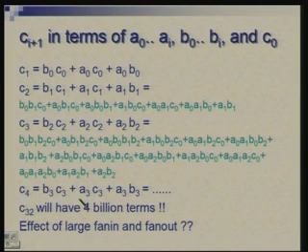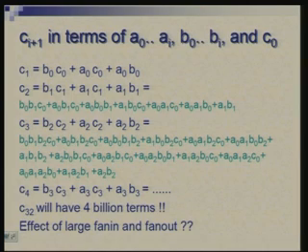The assumption we made initially, that the delay of each gate is constant, is possible only if the number of inputs, the fan-in, is not very large. But now you will have gates with these product terms that will become very wide. They will have 32 inputs. So, a 32 input gate will no longer have the same delay as a 2 input, 3 input or 4 input gate. So, although we keep things 2 level, our assumption about the delay of individual gates will break down.